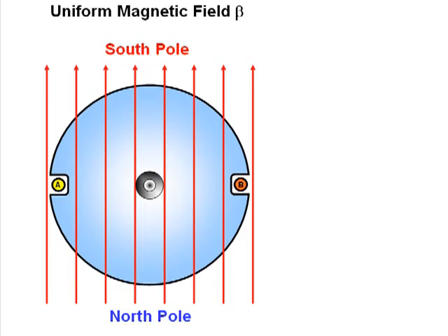Also, let's assume that these two wire segments are connected together behind the cylinder so as to form a loop of wire. We will define the flux which is threading through the center of this loop as phi, the Greek letter phi. From Faraday's law, we see that the voltage which will be generated from this end of wire A to this end of wire B is equal to the change of the flux which is threading through the loop.